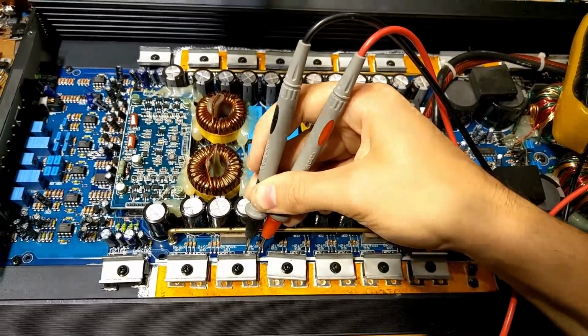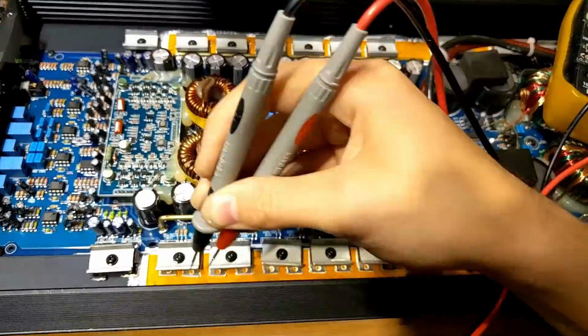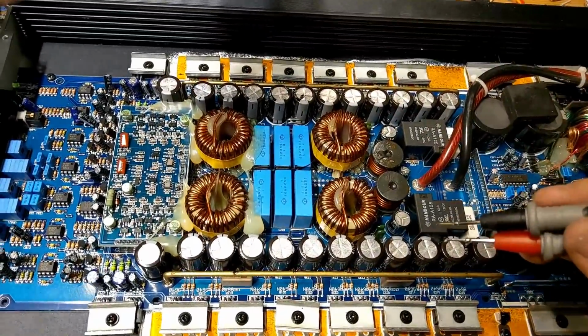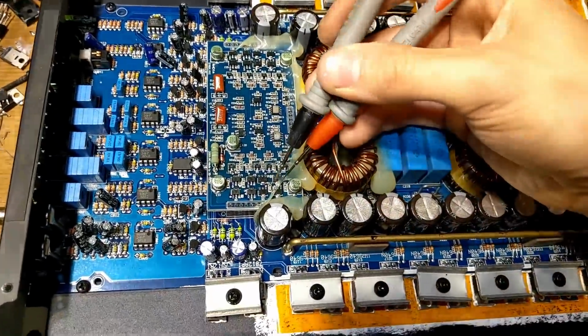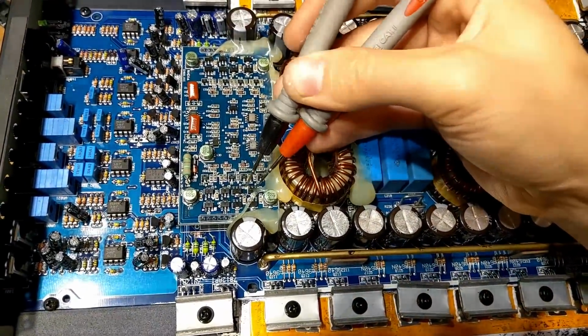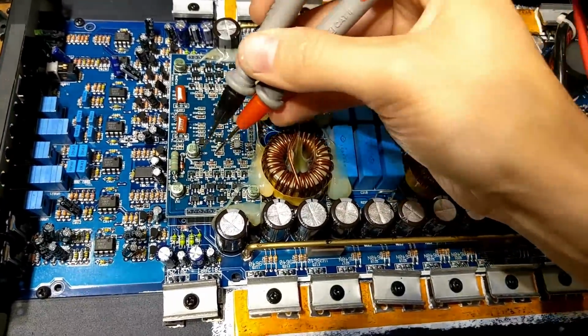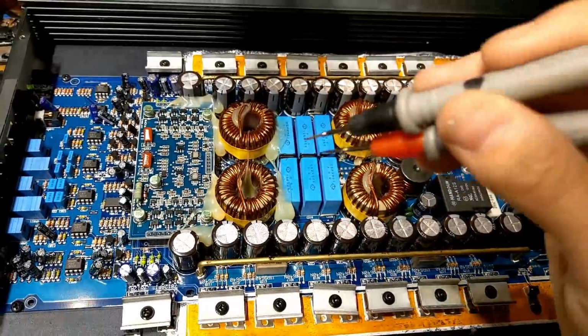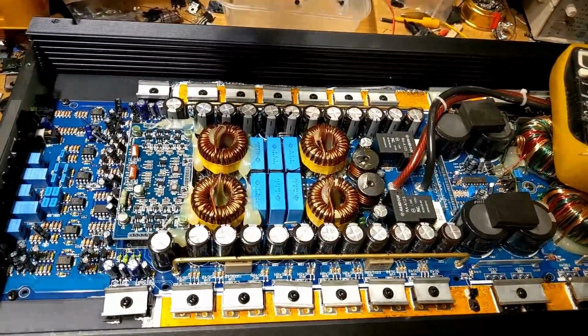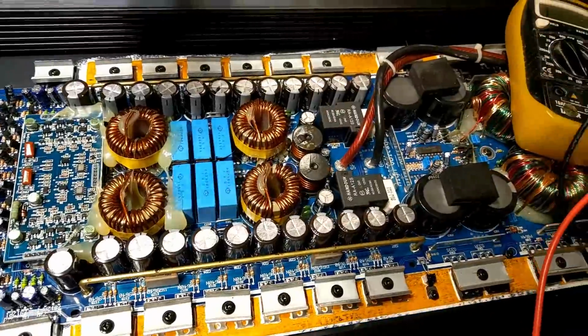However, given the age of this amplifier, it would make sense to just replace all of them because they might be on their way out in terms of lifespan anyway. When these die, sometimes it can kill the little drive transistors on the driver board over here, so it might be a good idea just to change all these anyway. These little parts are pretty cheap and it doesn't take too long to swap them out, so I might do that as well. Basically, just completely rebuild this amplifier with all the drivers and FETs and gate resistors, etc.